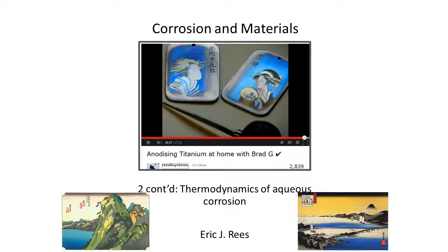And because the oxide is the thermodynamically stable phase of those alloys or metals, further corrosion pretty much stops once the surface oxidizes a bit. And if corrosion occurs but produces an impermeable solid oxide and then corrosion essentially stops, then the metal is called passive.